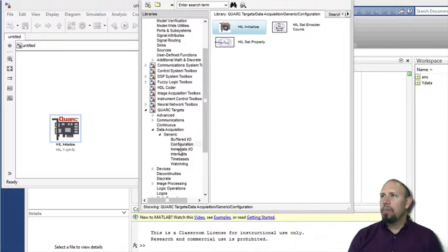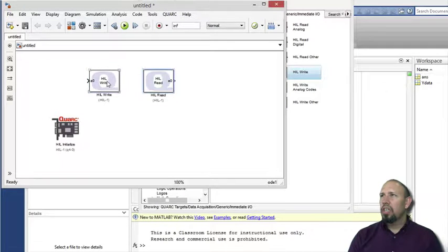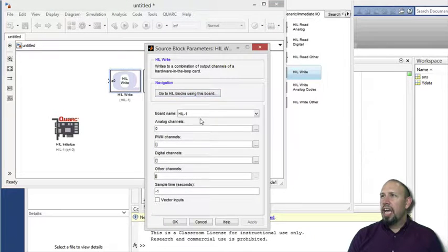Next, I'm going to go to immediate I/O and select HIL Read. There are a number of ones I could choose. HIL Read is one, and then I'm going to do HIL Write over here. Drag that over, place these here, and then double click, and I can change which channel I want to use.